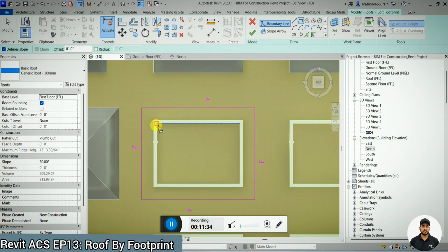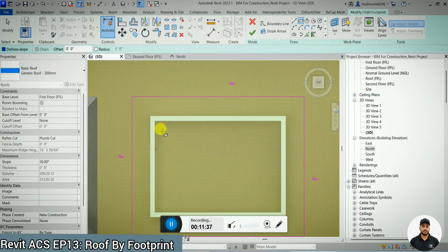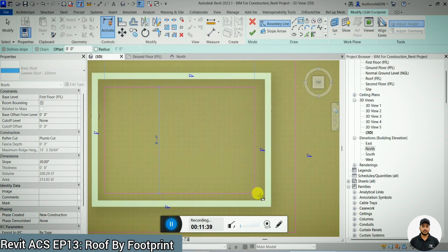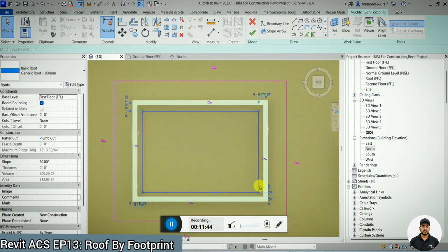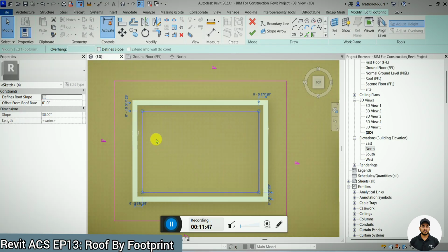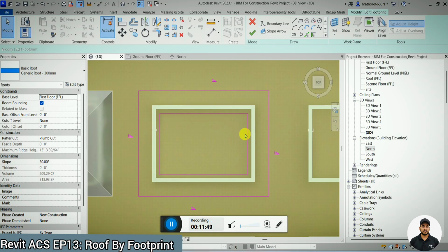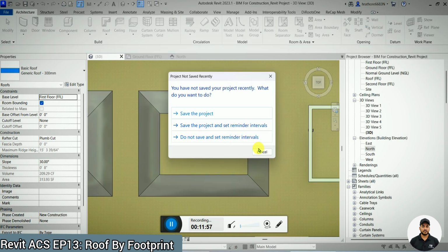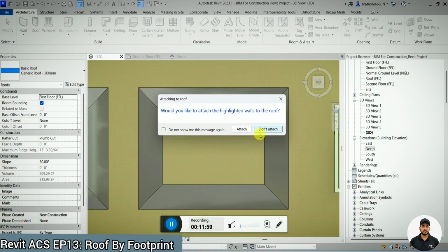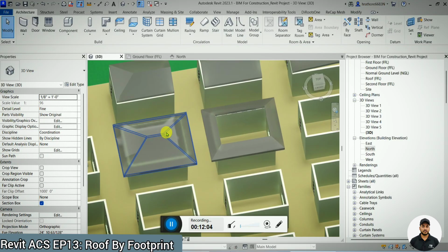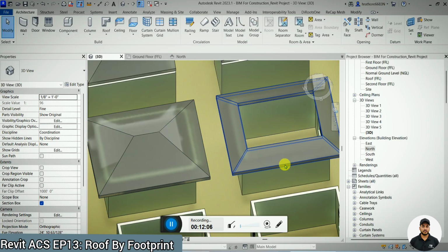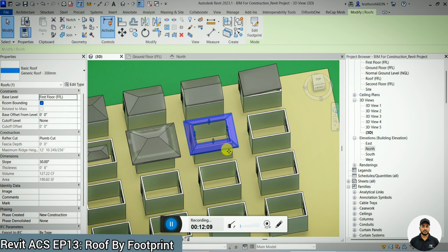If I create any geometry here, for example this geometry I have created here, and by choosing the tab I will turn off slope for all the inner edges. So whatever geometry we have created here, it will create an opening in the existing geometry. So we will click OK. As you can see here, an opening is created in the same existing roof that we have drawn. For example, this roof without opening, this roof with opening. So like this you can create the opening also here.